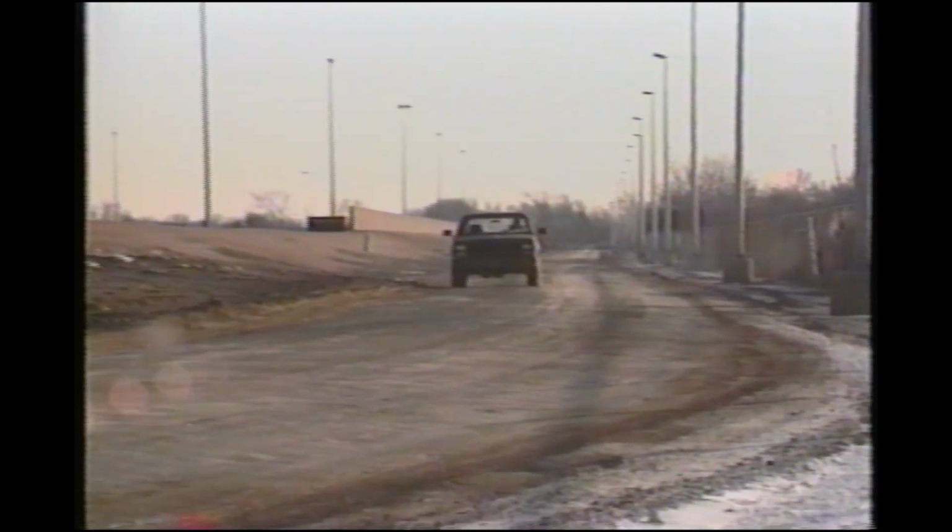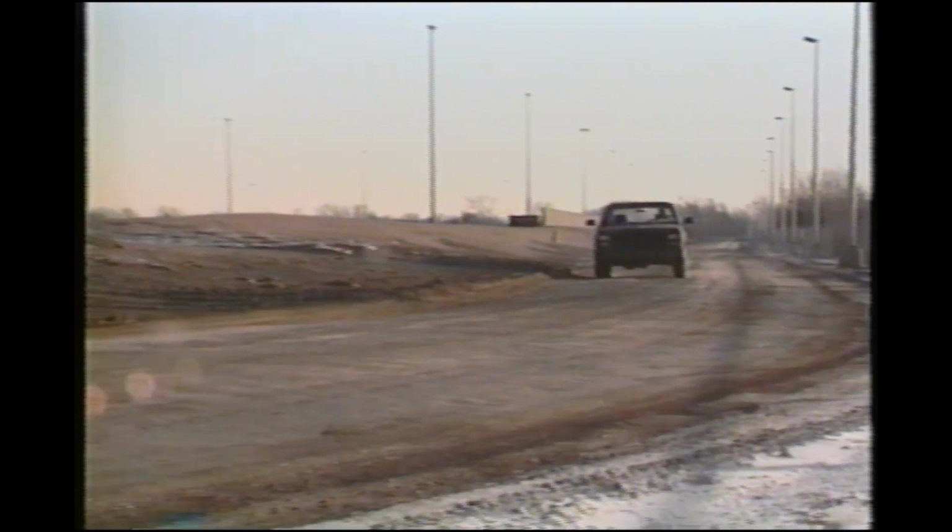As a tire rolls down the road, heat is generated. If the entire tread is in contact with the road, this heat is minimal and can be readily dissipated. An improperly inflated tire creates more heat than it can dissipate. This causes the rubber and cords to literally burn up.